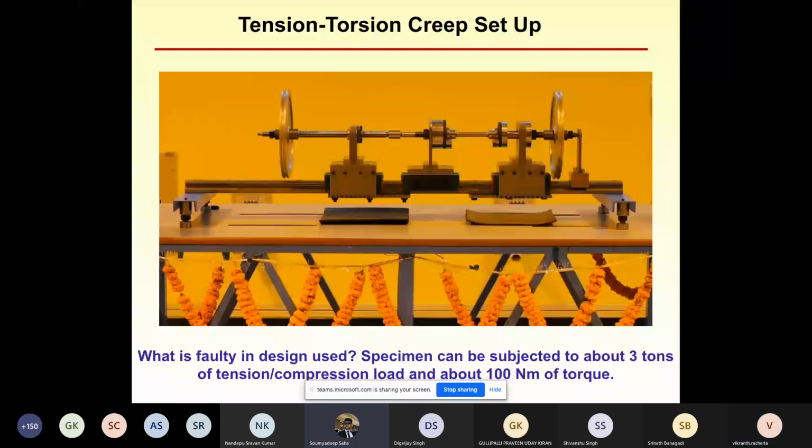Okay, fine. So this middle rail block can slide freely along the rail. The outer two rail blocks are fixed. And then we have made these columns. The columns are rigidly attached to this rail block. Let's call this a column. So you have these structures over here. Now, in order to apply tension, we have a tubular specimen. What you see over here in the middle, where the laser pointer is right now, that is the specimen which we want to subject the load to and whose deformation we will monitor.